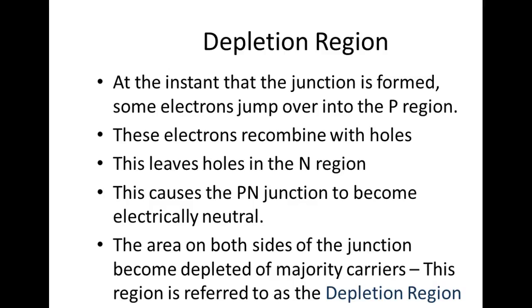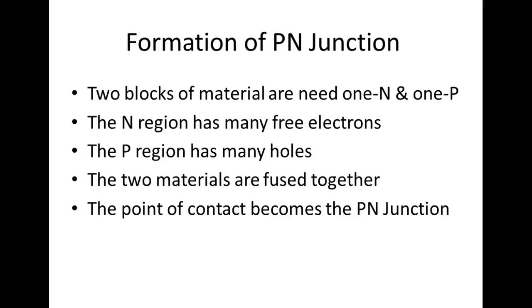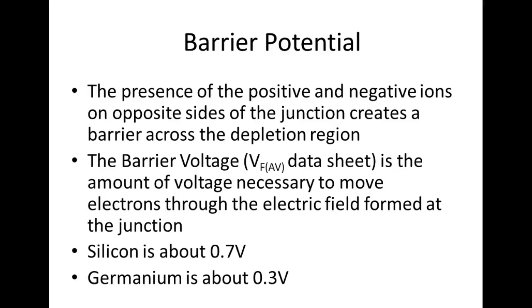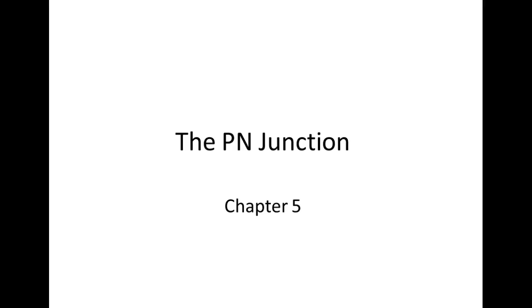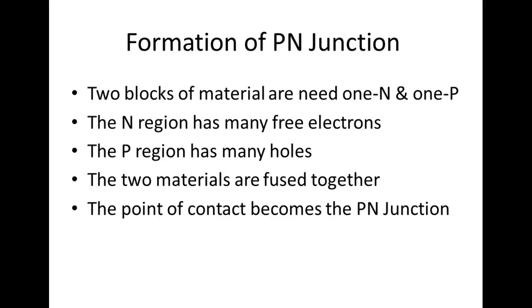So what we do is we deliberately, we call it doping, or they call it doping. I had nothing to do with these names. So what we do is we introduce a pentavalent, which is an atom with 5 electrons in the valence shell, and then we force that into the crystal, and then it'll bond.